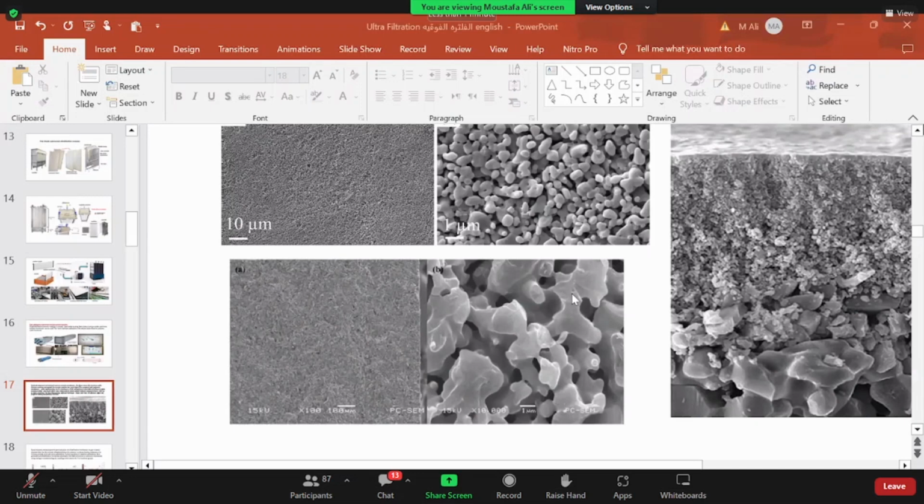It's the same technique, just to make incipient melting for the edges. In such a case, because the particle size is very tiny, the edge fusion will not require very high temperature. So we are doing it at a lower temperature limit. So this is for silicon carbide.